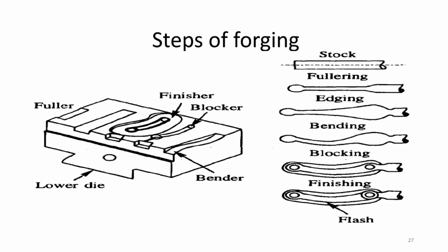For steel it is 11 multiplied by 10 to the power minus 6 per degree Celsius, while for brass it is 19 multiplied by 10 to the power minus 6 per degree Celsius. So it's higher in case of brass, so brass will show more expansion compared to steel.